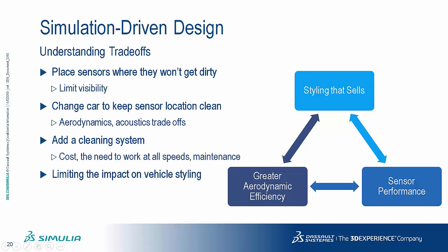Okay, so using simulation, we can move the point at which you're able to look at this soiling and water management to much earlier in the design phase, because typically we're only able to look at this through experiment very late, after we've got some test vehicles, because we have to do real-world on-road testing or track testing to get this kind of information. But by moving it into simulation, we're able to do it at the same time as we're doing acoustic simulation or aerodynamics or thermal simulations. And that way we can make the proper trade-offs.